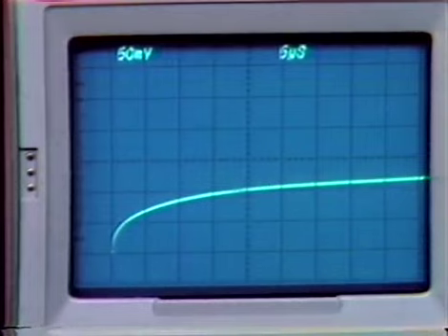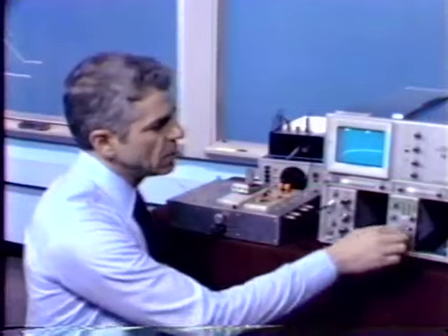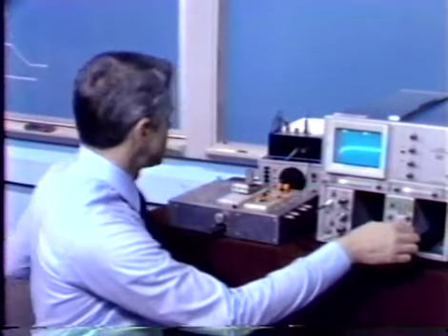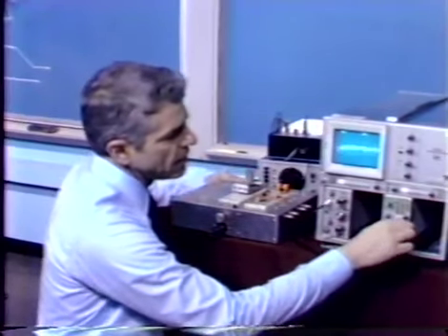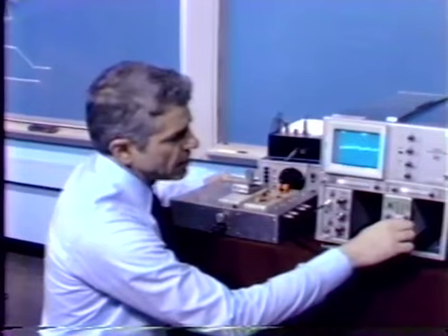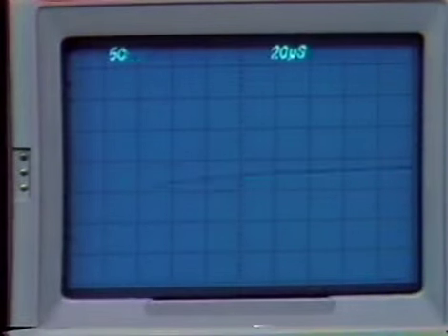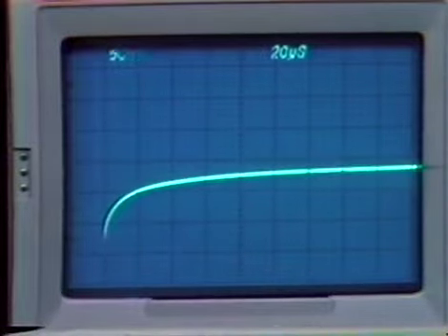We go halfway or so to final value quite quickly. We go halfway in a few microseconds. We're at 5 microseconds per division. 1.5 divisions vertically is half of final value. But 500 microseconds later, we're still settling. And in fact, if we examine things very carefully, half a millisecond or 5 milliseconds later, the transient response is still settling. And that reflects the collection of closely spaced pole zero doublets